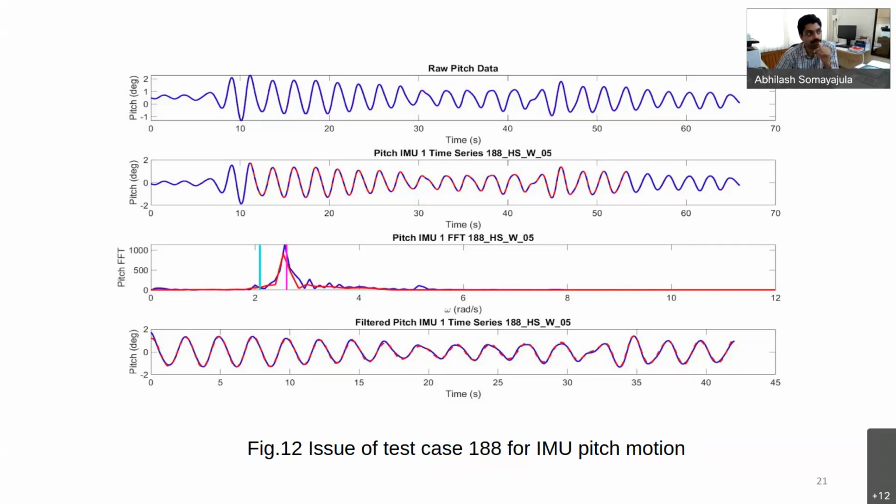If I move that into an inertial frame, then I can take the FFT of the signal and do the similar process of cutting off the frequencies away from the area of interest. Whatever amplitude I get, I divide it by omega square because I precisely know the omega that I wanted to simulate it for. Since it's acceleration, it should be minus omega square times the amplitude. So if I divide by the omega square, I should technically get the amplitude for the Heave. Technically. That might be the best approach, I would think, rather than attempting to integrate it.